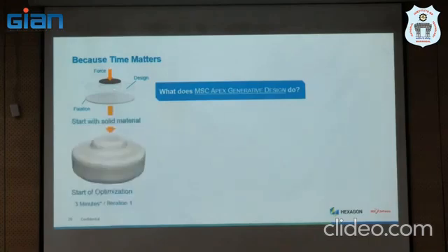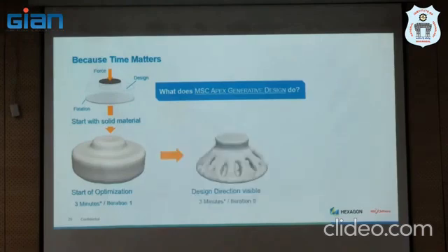It will apply the load on the given component, then it will understand how the stress is distributed within the volume. Every material has its own UTS. So it will compare the stress with UTS in each element. Wherever it is less than UTS, it will remove or delete that element, so that it will become lighter.